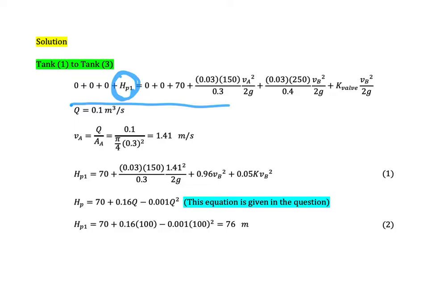So that's why in this movement we found that water could travel from a lower place to 70 meters above the datum. Why could the fluid elevate this high? Because it gets extra energy from the existence of the pump here.